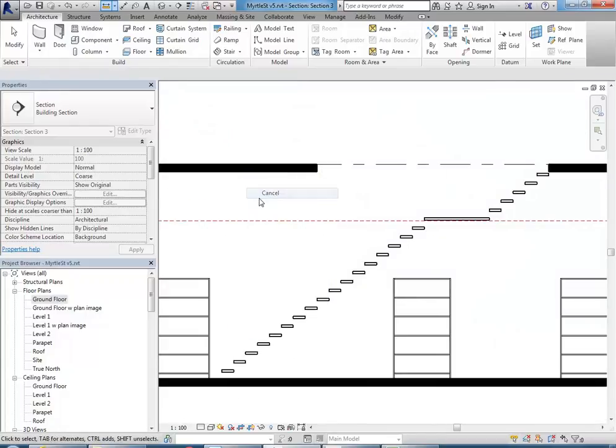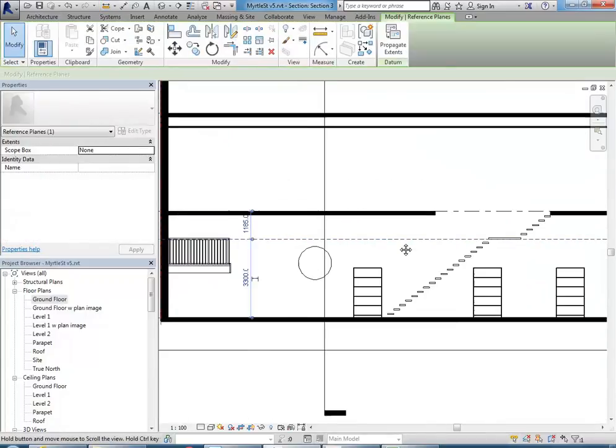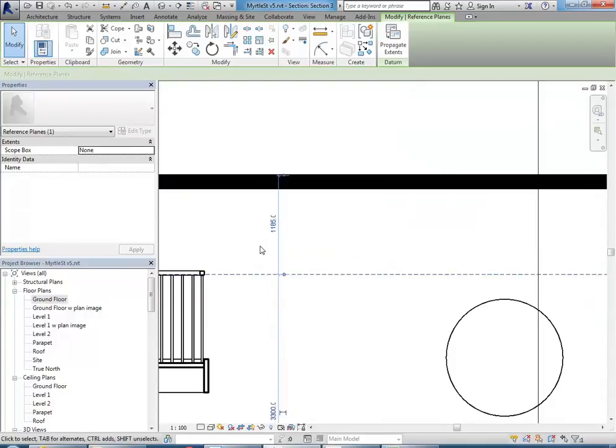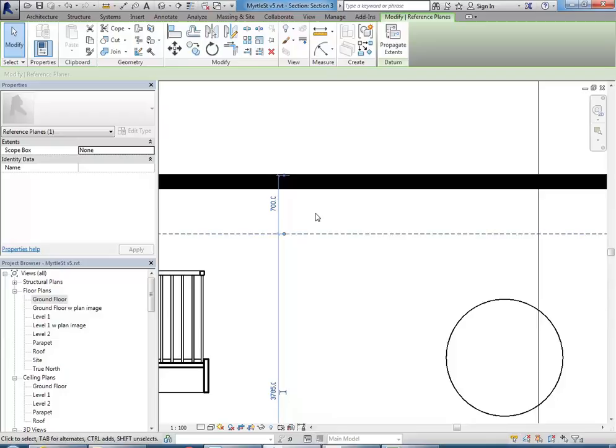But we're going to have a ceiling. So again, I've put this reference plane in to help me work that out. I've got a pretty decent bulkhead there at the moment, but I've brought the level up, so I'm going to bring that reference plane up as well to, let's say, 700. Yeah, 600, so it'll be 600 below the floor. So, yeah, 700, that'll leave me 550. That should be enough.